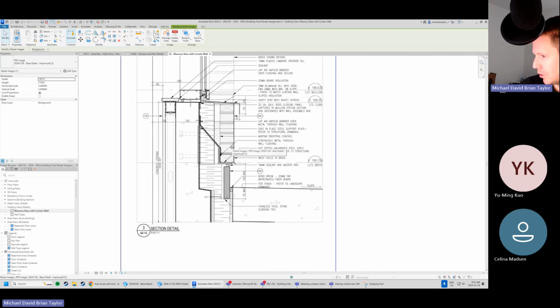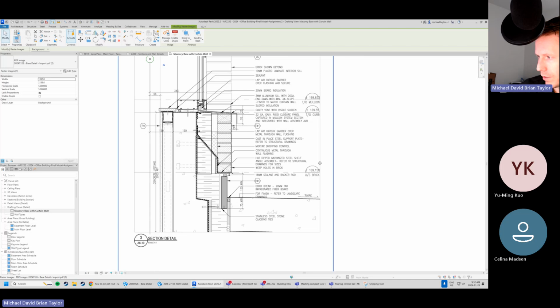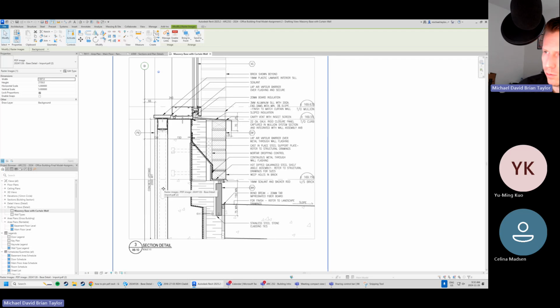And so typically the drawing process that I like to do is I want to get as many of the datums in first. The datums being things like my grid, things like my bubbles, and then start to draw the structure. So I like to draw the structure second. And then I like to draw the membranes, right? And then the insulation, and then the cladding. And then sometimes, if we do have some interior elements, we can come back and draw those. So that's just the process that I like to use. You're welcome to use whatever process you want to do.